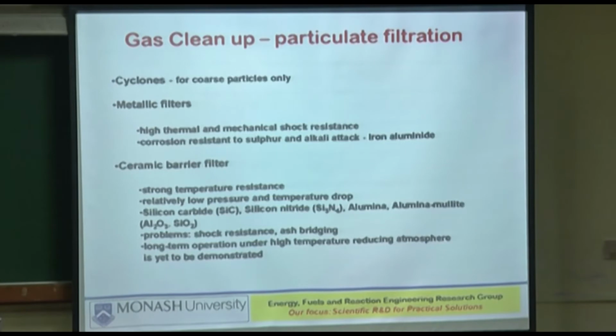The other thing is ash bridging. So if you have two candles coming down side by side, then if there is ash buildup, obviously they can bridge. The ash can form a bridge, and the ceramic candle filters do result in, I wouldn't call it promote, but they result in more ash bridging than the metallic ones.